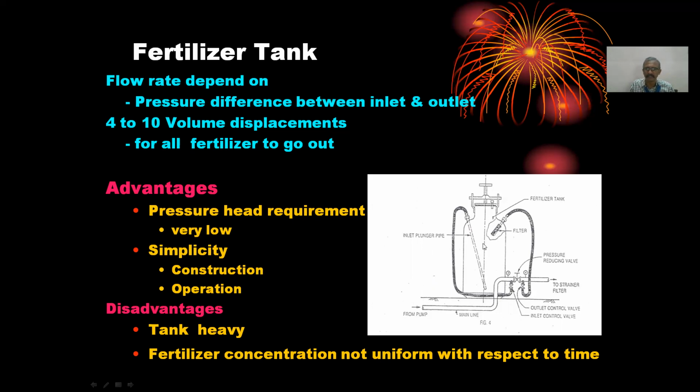very huge, heavy tank. And fertilizer is placed inside this fertilizer tank, and when water from here goes in, it gets dissolved, and the fertilizer mixed water will come out and it joins at the other side of the valve, at the upstream side or the downstream side of the valve, and the fertilizer mixed irrigation water keeps going. So whatever be the pressure, if the system is functioning, and it will function. So pressure issues it does not have, but it is costlier than the Venturi.